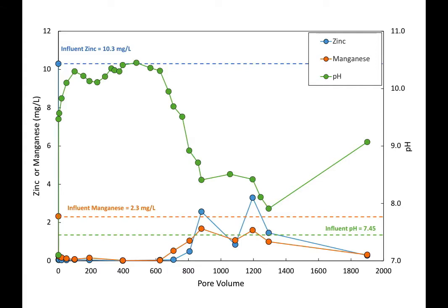The Palmerton Superfund zinc site is in Pennsylvania. Palmerton, Pennsylvania is the big flagship kind of model for this one, and they were the ones that were actually producing IRM as they were in the facility using the electric arc furnace. So they had tens of thousands, millions probably of tons on site, a tremendous amount of this IRM material. And when they shut down, they had a groundwater plume of zinc upwards of 150 milligrams per liter of dissolved zinc in the groundwater. And what they did was put a mile-long trench and loaded it up with the IRM. And they did that in '77, I believe.